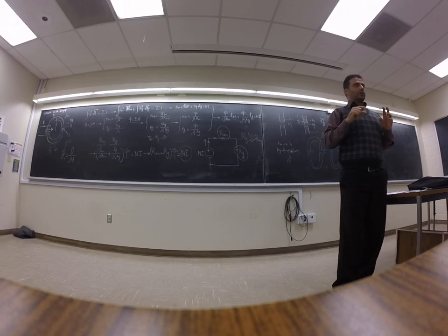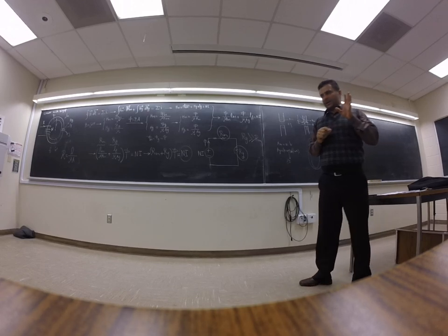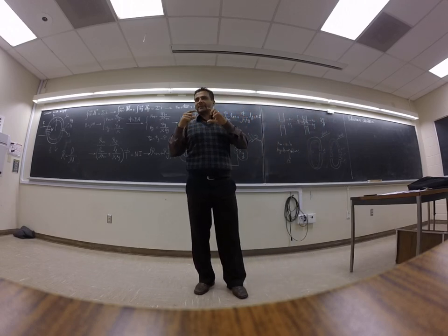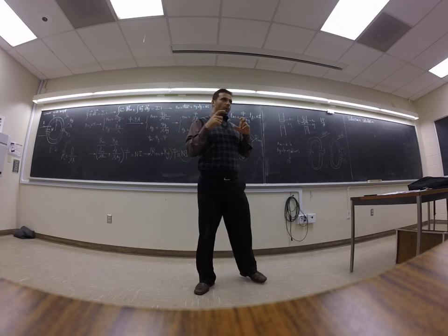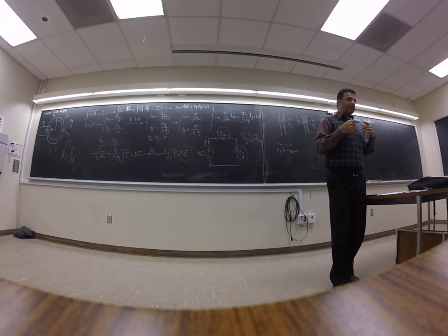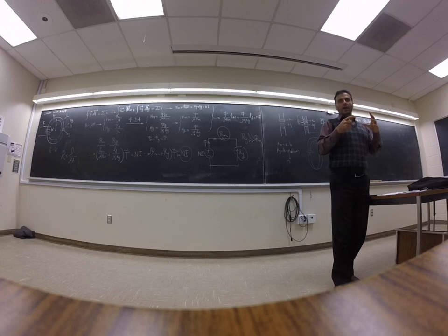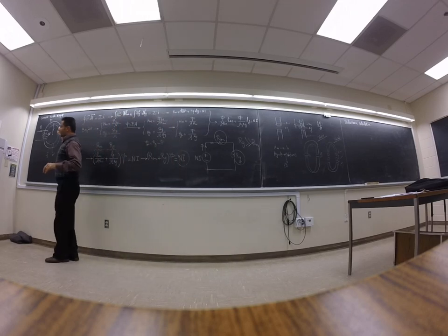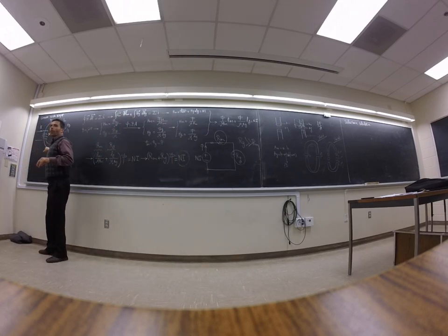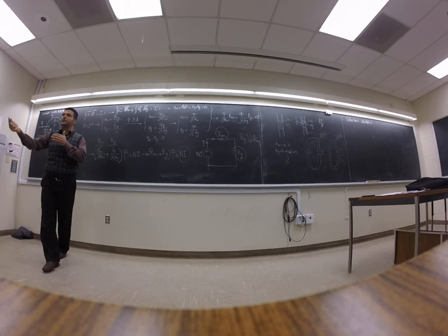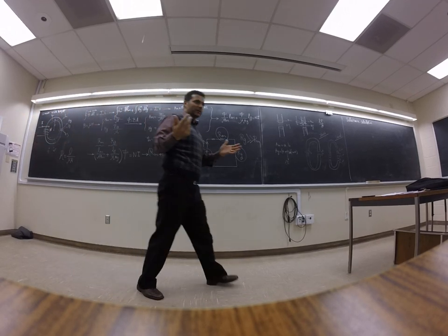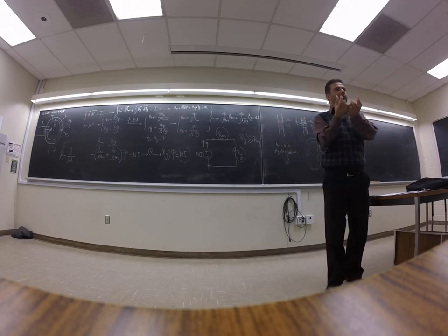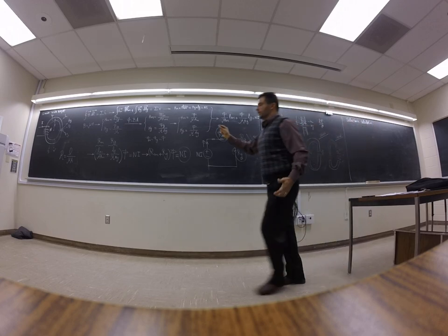What they do with those ones, they are like a donut. Each of them has different characteristics. But usually they mix the magnetic material with some non-magnetic material, like glass, something like silicon. Think about it: this is kind of central here, and they distributed this one all over. You know what I'm saying? Mixing it with something non-magnetic basically reduces the magnetic capability of the core a little bit, but it's completely uniformly distributed on the core. This one is just central, it's just here.